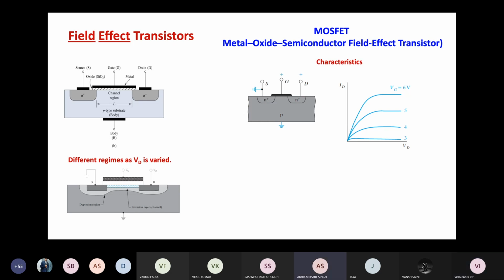This means that because it was a minority carrier, we do not want it to dissipate somewhere else. That's why we have put that metal oxide. If this interface is not good, there might be an electric field, and this thin layer may be absent from some places. It may have irregularities. Two MOSFETs will not be similar to each other, so we cannot use them in a circuit. Those kinds of reliability issues arise when this insulator is not properly lattice matched to the channel.